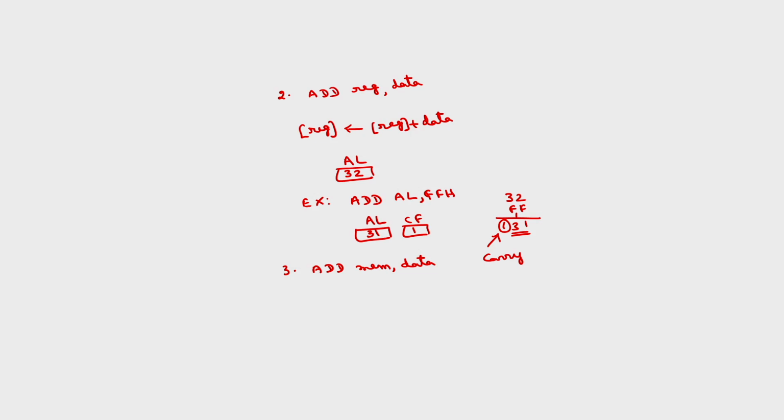Okay. So, these are the 3 ADD instructions, and then there are 3 ADD instructions with carry; these are without carry. For example, if I want to add multi-byte numbers, 72554F32H plus F210FECAH. So here, if I use 16 bits at a time, because 8086 is a 16-bit microprocessor, it can perform this 16-bit addition in a single clock cycle.